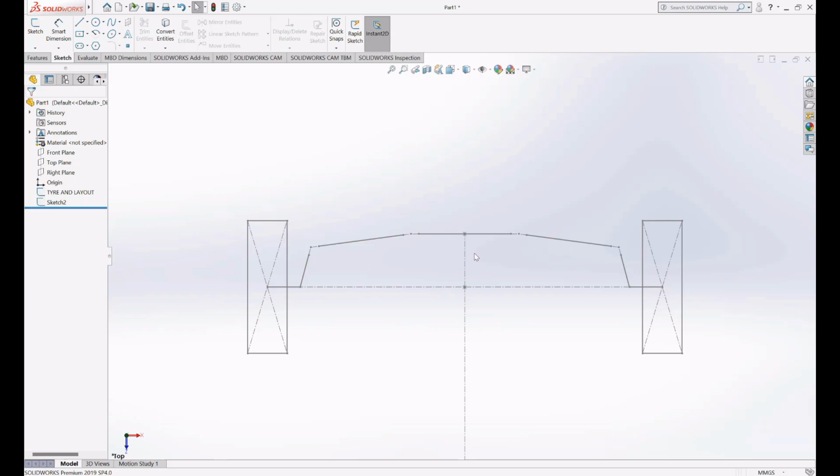What we have done right now is understood the construction process, how to make anti-Ackerman steering geometry. There are a lot of technical things like the positioning of the steering rack, the steering arm angle, spindle length, steering arm length, steering rod length, and steering rack length. These are the design parameters which will affect the performance.